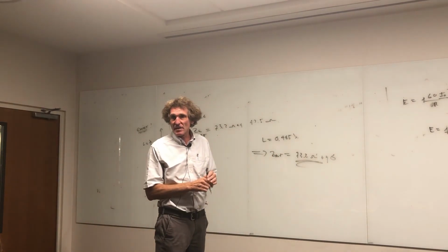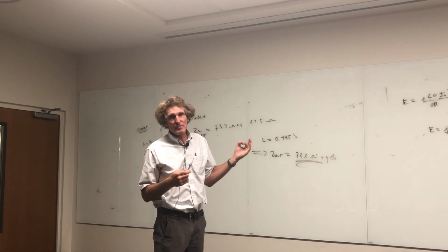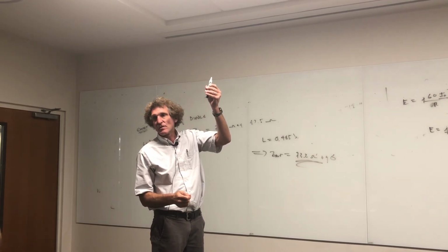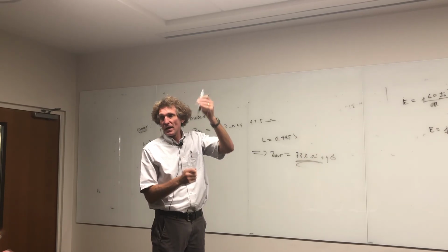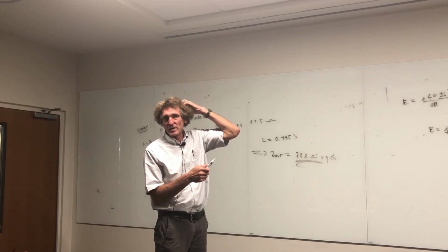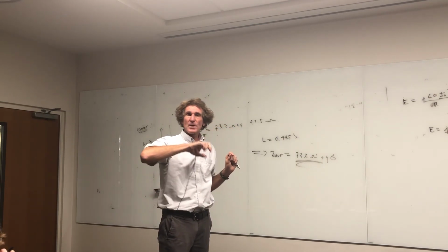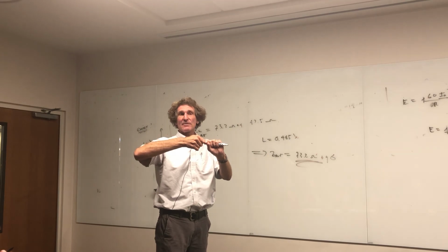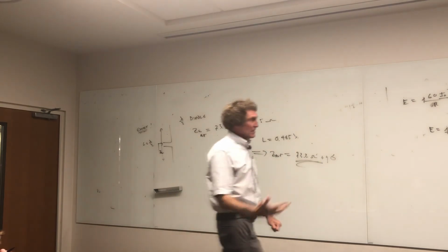The way they make these things is literally they just start snipping off the ends because there's so much that causes that input impedance to change. Everybody thinks it's an ideal straight piece of wire, right? Well, let me tell you, long wires aren't straight. They wobble, they have bends that cause slight changes at the driving point. And the way you always do it is tweak. You always build in system tweaks. You all know how to put in a variable resistor, a pot. If you need exact resistance, you'll put in the bulk of the resistance as a single resistor, and a potentiometer that you can adjust to the exact resistance you need. Follow me? That's the way it's done in the real world with antennas too. You snip them off when you're doing antenna design.